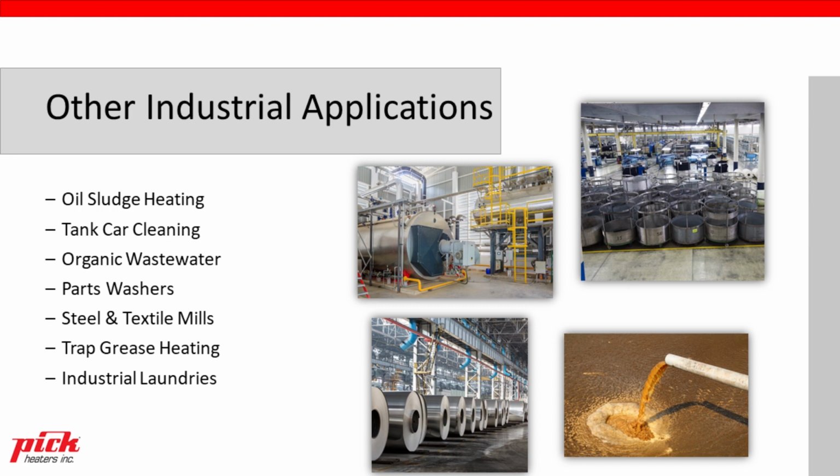And then other industrial applications that we've tackled over the years, anything from oil sludge heating, where they're reclaiming oil from large tanks, to tank car cleaning, and also tank car heating. So two common applications where, again, during the cold weather months, heating and cleaning are an advantage, and steam injection is very quick at the point of cleaning.